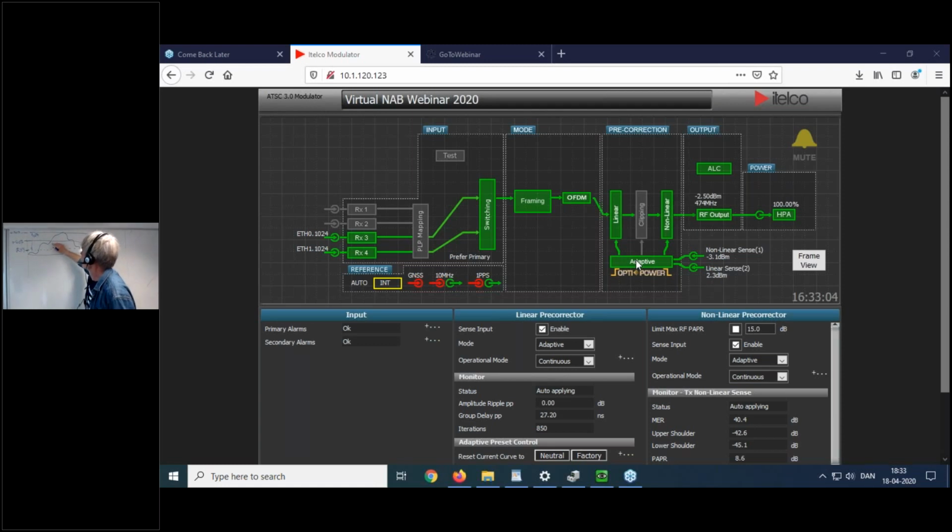The amplifier only has the capability to reproduce the signal like this, then it hits saturation in this area. Instead of following the waveform with fidelity, which is bandwidth limited, meaning there is a limit to the rate of change of the signal, when we hit a hard limit, like the power supply, that actually creates discontinuities.